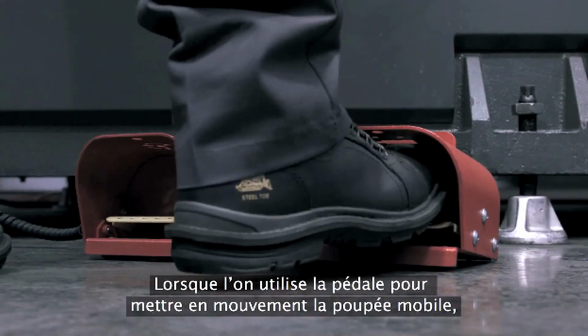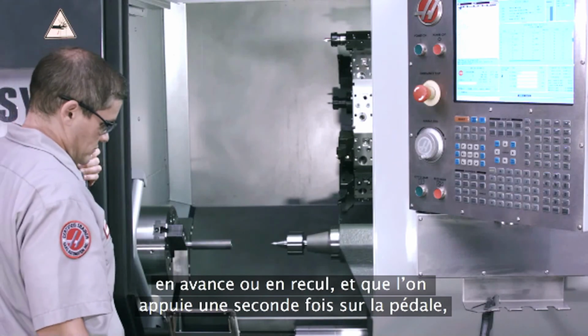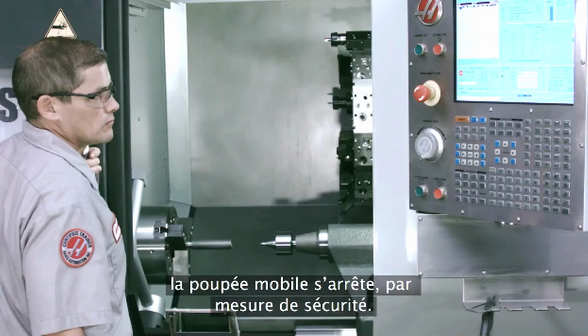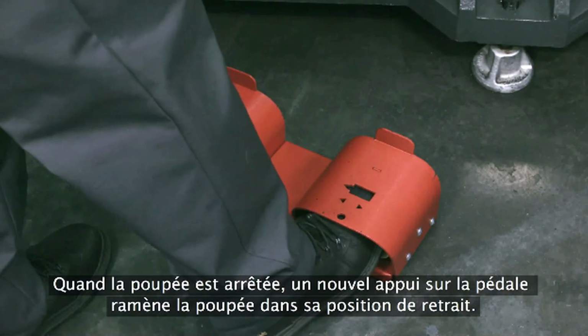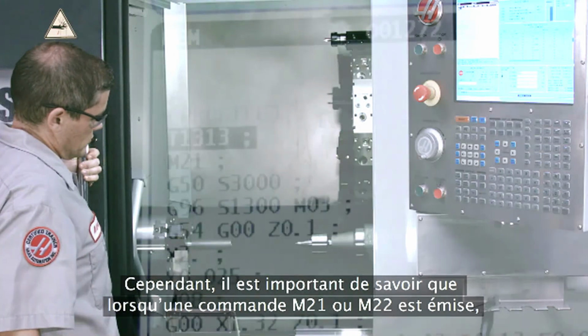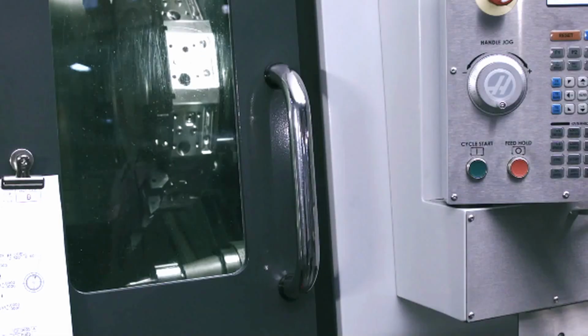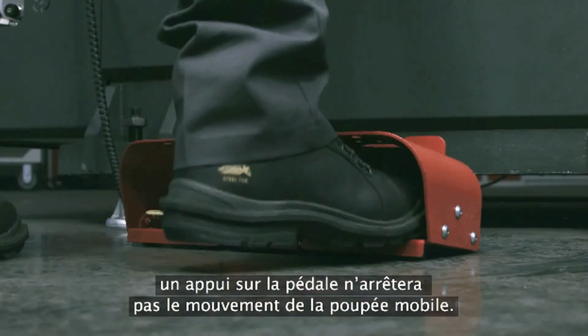When the foot pedal is used to put the tailstock in motion, either forward or in reverse, when you press the pedal a second time, the tailstock will stop, as a safety precaution. Once it's stopped, pressing the pedal again will return it to the retracted position. However, it's important to note, when an M21 or M22 command has been issued, pressing the foot pedal will not halt tailstock motion.